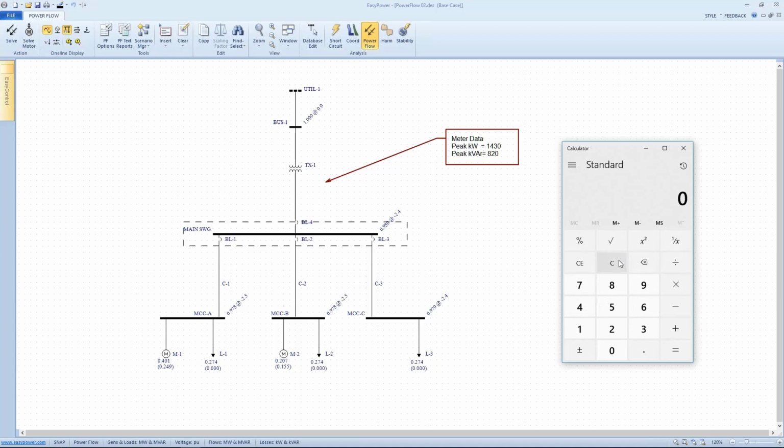Because it's where we have a discrepancy that we can focus either preventive maintenance or preemptive elements, such as coming in and doing an infrared scan of equipment in a branch that appears particularly lossy, because it could be poor connections, it could be poor elements, it could be insulation wearing down. There's a number of elements that could be causing the problem.